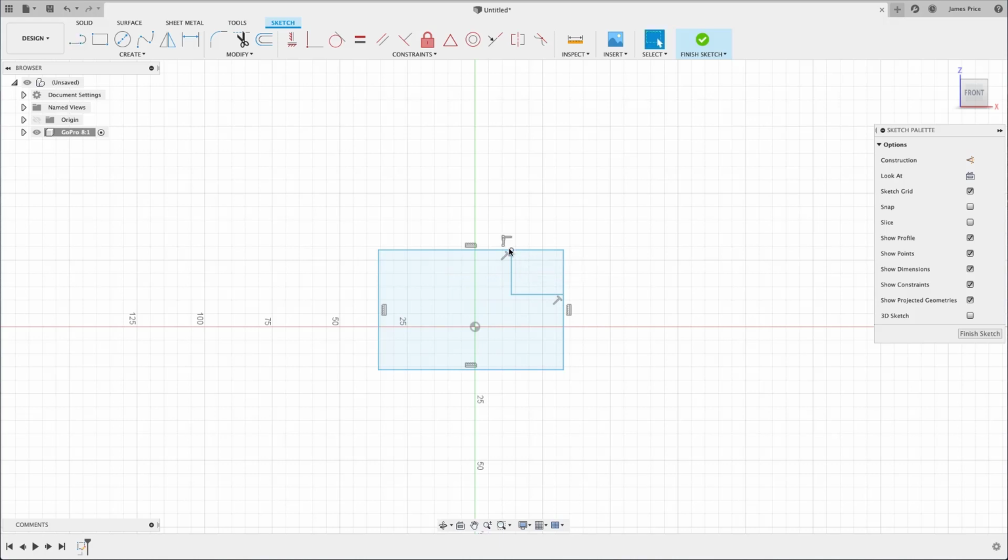We have our base sketch in position, so we can now look at the next step and modifying this by applying some fillets. I'd like to note here that in general, you may prefer applying fillets using the 3D command instead, as you can find these easier to assign and manage across multiple components and more complex designs. Once you become more familiar with Fusion, you'll find a method that best works for you, although for now, we'll apply these as 2D sketch features.